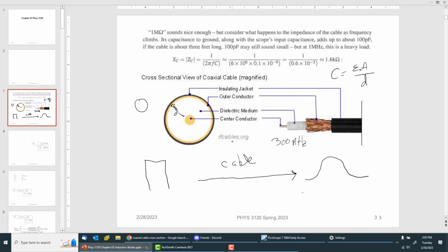But that's another discussion. But if I have a bare wire, even a bare wire, that's one of the reasons I pushed you to move away from those adapters with the BNC adapters and the banana cables, because a bare wire has a capacitance. Even though there's no other wire or conducting plane, there is effectively one. It's sort of like an impedance, isn't it? But there's a capacitance of any bare wire, or two wires next to each other.